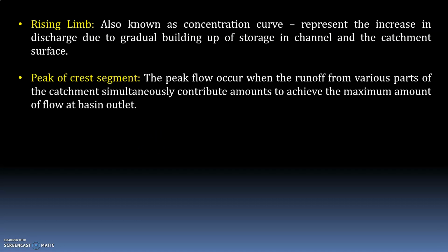Let us take the second point, the peak or crest segment. The peak or crest segment includes the part of the hydrograph from the inflection point B on the rising limb to an inflection point C on the recession limb. The crest segment is one of the most important components of the hydrograph because it indicates the peak flow rate.